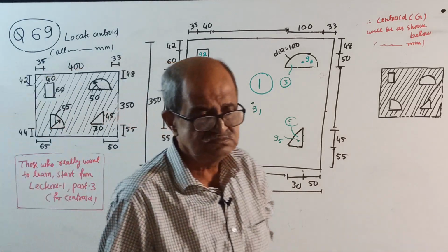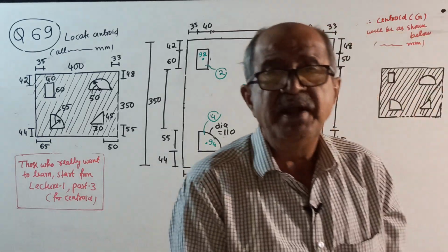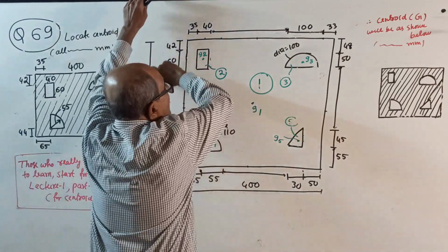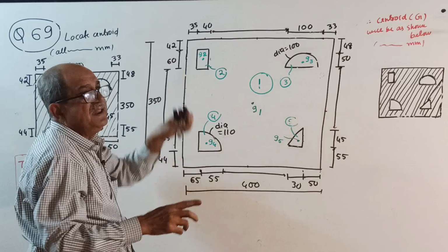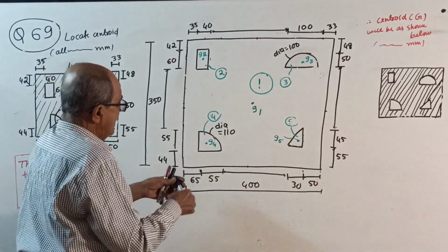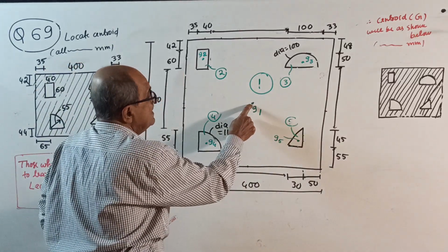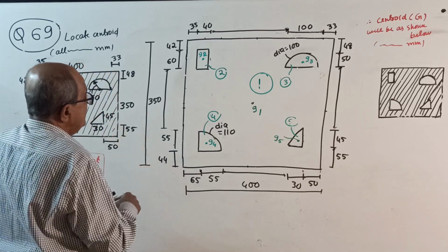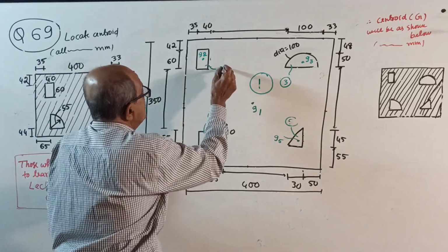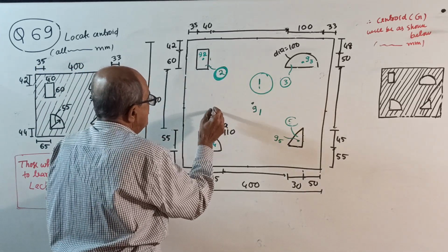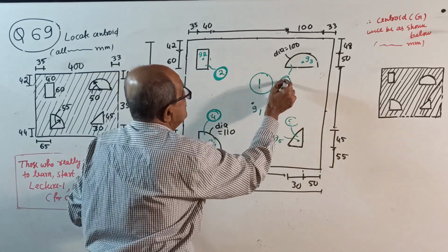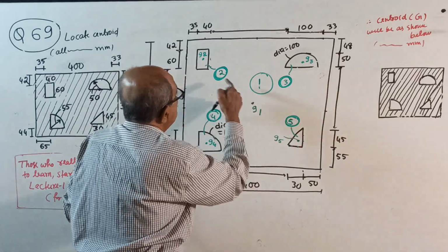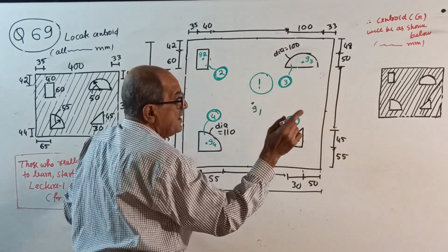Okay, now, how to divide into parts? Very simple. Figure number 1, make a note here. 1 is full rectangle. I won't write A, B, C, D like that. You can make out. For that one, centroid is here. See, this way midpoint, this way midpoint. Now, be careful now, your 2, 4, 3 and 5 or 2, 3, 4, 5 are all cut out.